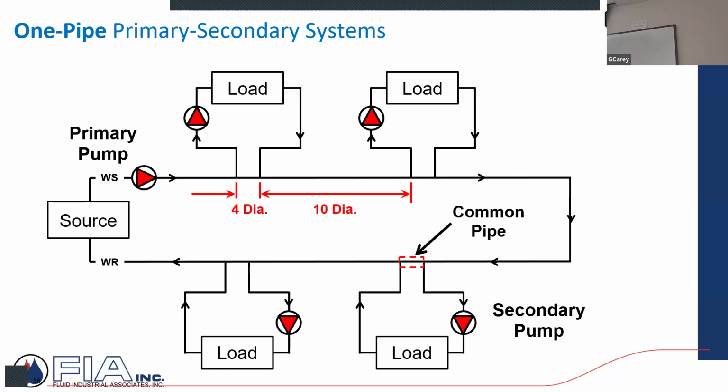And to your point earlier, if I have this scenario, what happens as I take heat up through this load? The temperature that was at that T can't be the temperature at this T, correct? I have temperature degradation. So the supply temperature here for this load is going to be different than the supply temperature for this T, for this load. So one pipe, I've got to account for that. So it's more about information.